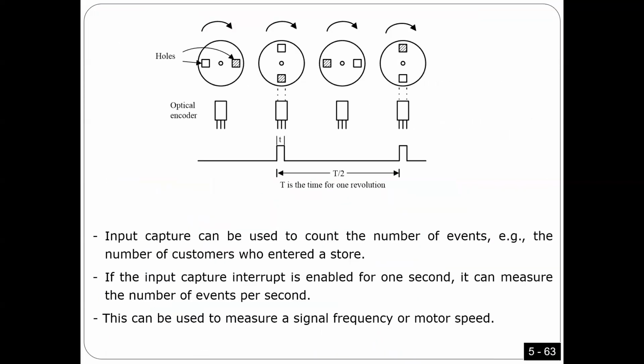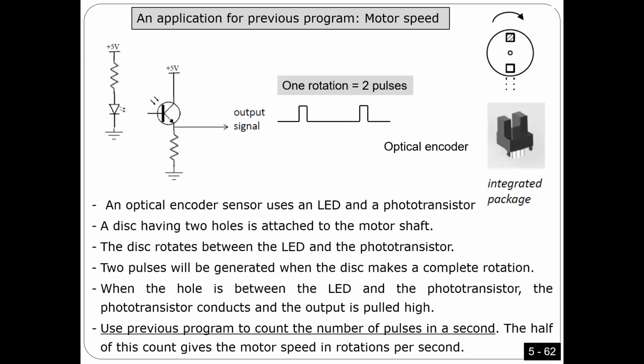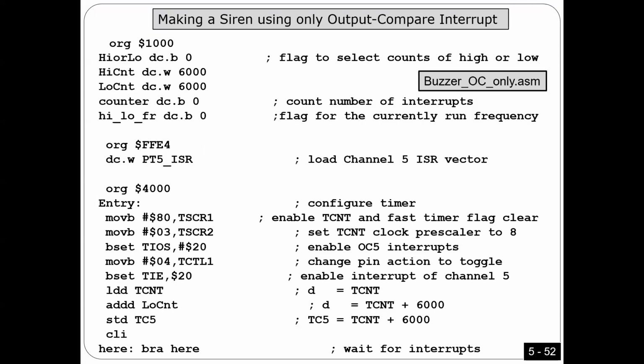Also, keep in mind, this is the beauty of these topics. I want to measure the time with very little time from the CPU. The CPU itself can do the measurement, but the beauty here is that most of the work is going to be done by the external circuit, so I take very little time from the CPU. This is the key point here. This is what you mean by input capture.